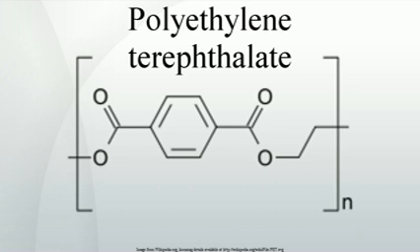Simple repelletizing of bottle flakes. This process consists of transforming bottle waste into flakes, drying and crystallizing the flakes, plasticizing and filtering, as well as pelletizing. The product is an amorphous regranulate with an intrinsic viscosity in the range of 0.55-0.7 dl/g, depending on how completely the pre-drying of the PET flakes has been done. A special feature is that acetaldehyde and oligomers are contained in the pellets at a lower level. The viscosity is reduced somewhat, and the pellets are amorphous and have to be crystallized and dried before further processing.